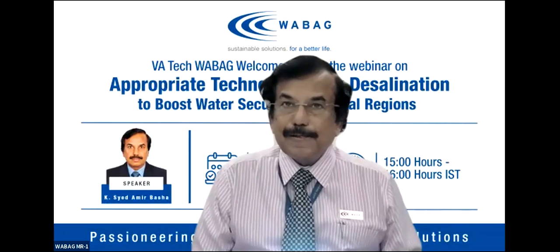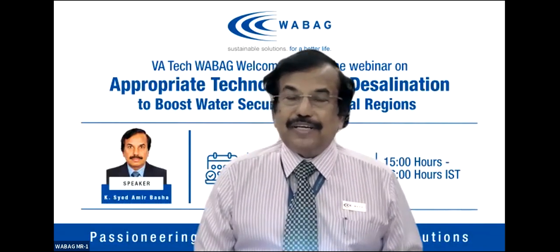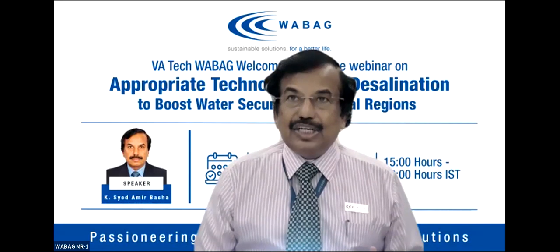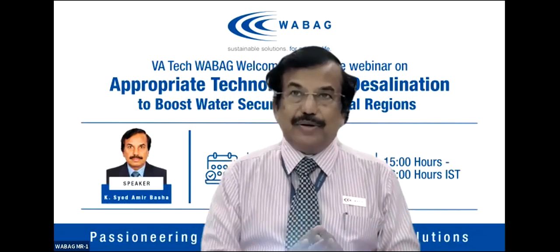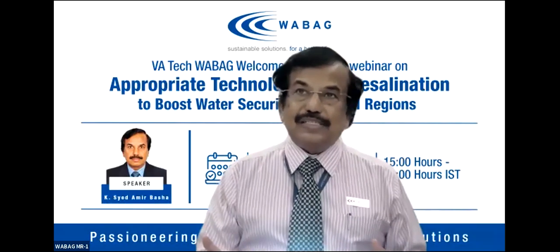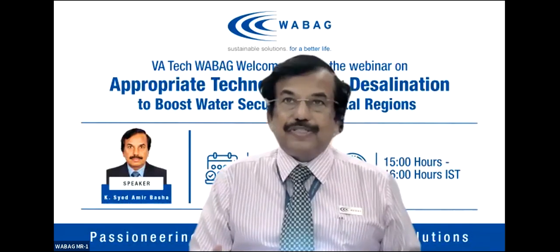Thank you. The next question is from Mr. Nitin N. What is the criteria for choosing between lamella clarifier and DAF? Lamella clarifier is for total suspended solids, whereas DAF is for light particles like algae, TOC reduction, as well as oil traces. So they have two different functions and they work on two different principles. One is the settlement principle, the other is lifting the particles with air and then skimming them off. So they work on almost opposite principles.